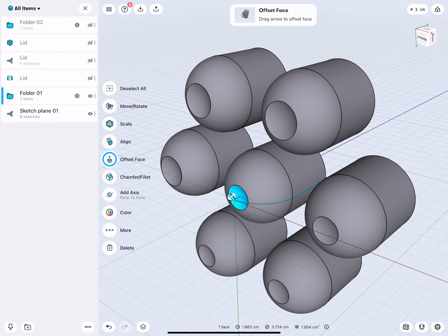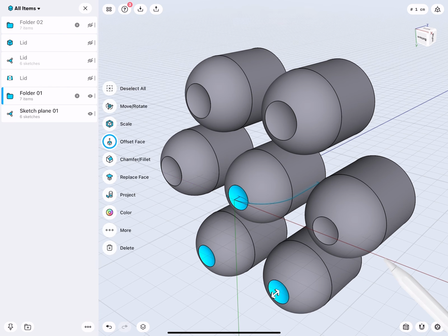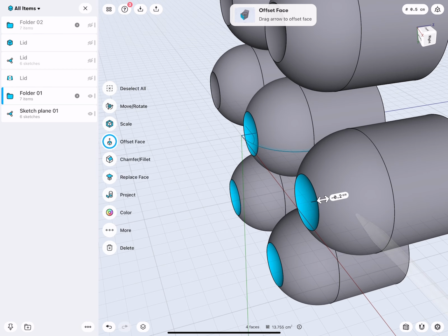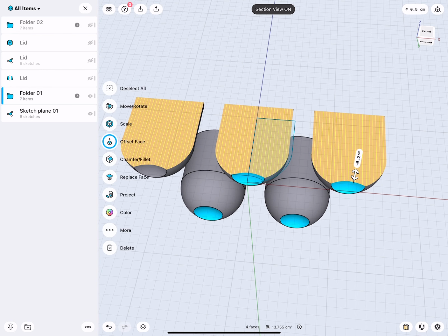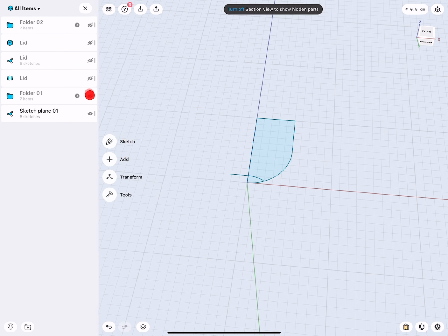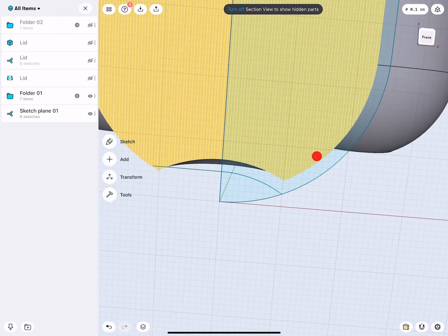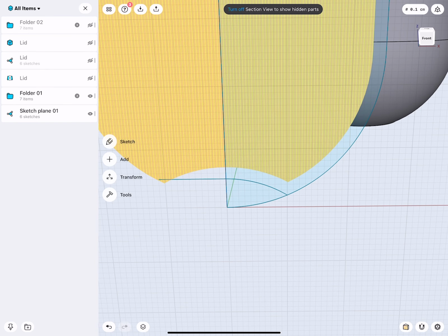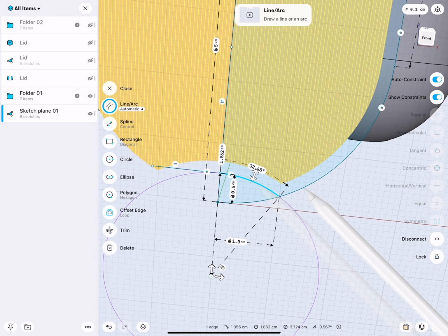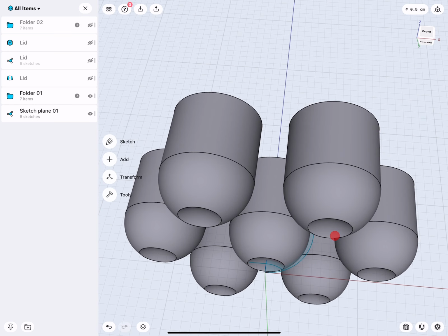So we can do this one by one, or we simply select all and then do them all together. There we are. Let's double check. We do a cut section, take a look at our filled pieces, turn this on and off, and try to see where our objects are. Yeah, no, this works really good. Even in the sketch here, you can see how the domes, which we offset to the inside, have a perfect flow. Good.